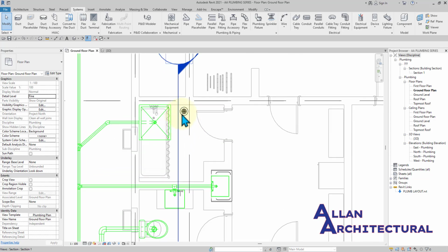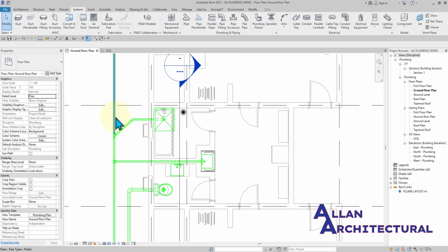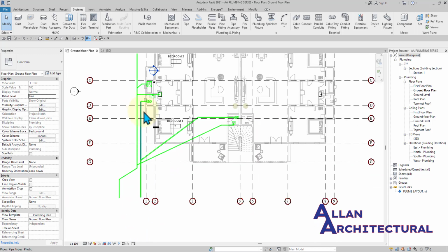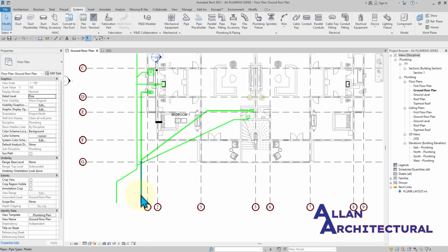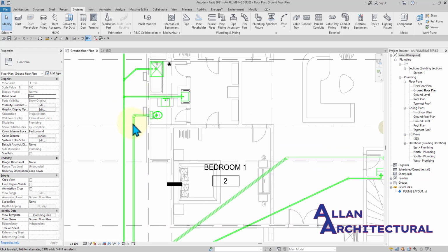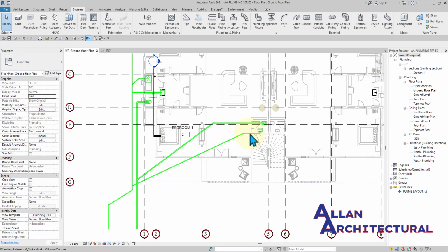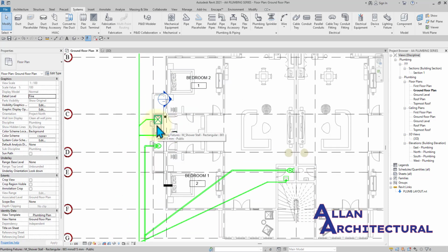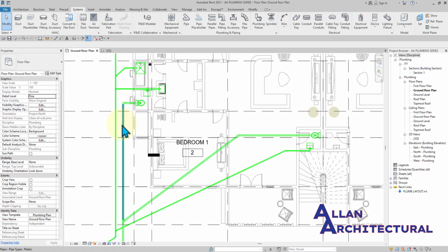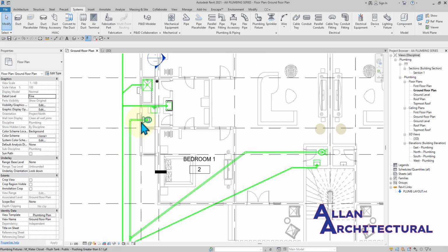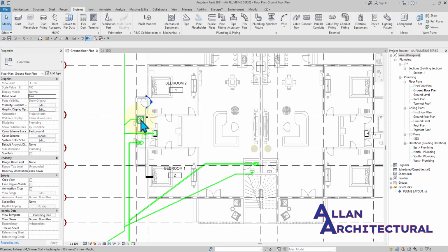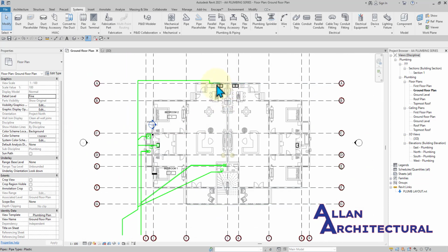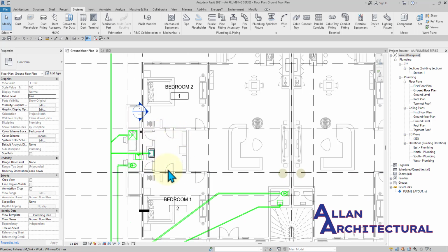Alright, so we have this floor drain in here, and we need to connect that to this pipeline. Like I said earlier in the previous part, you notice all of my pipelines are not being connected on the same line. The WCs have a different line, and then the wash hand basins and the sink also have a different pipe connection. That is because some engineers have discovered that we tend to have the gases inside of the WC's pipeline. They tend to smell and come all the way through maybe our kitchen sinks and the wash hand basins, and it makes the area smell.